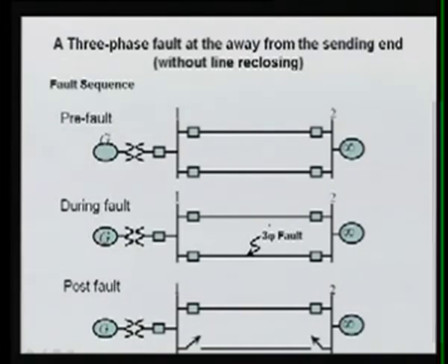Now the system impedance here is different: during the fault the impedance is different, and after tripping it is different again. In this case, what will be your X? I am using X as X D prime of the generator, XT of the transformer, plus XL1 parallel to XL2, if you remember the value I was using in lecture number 6.